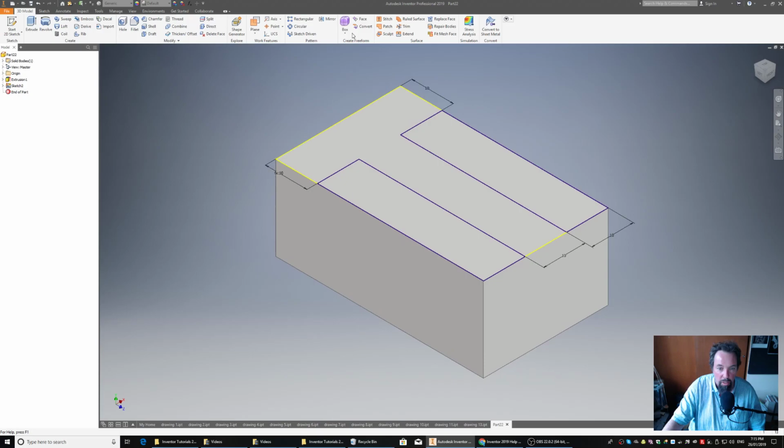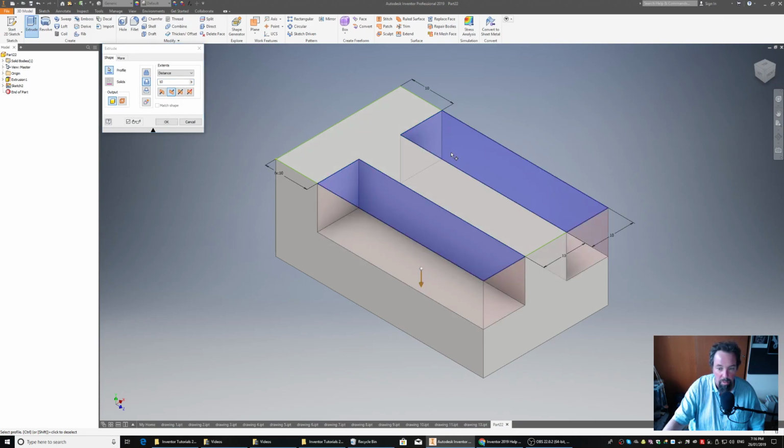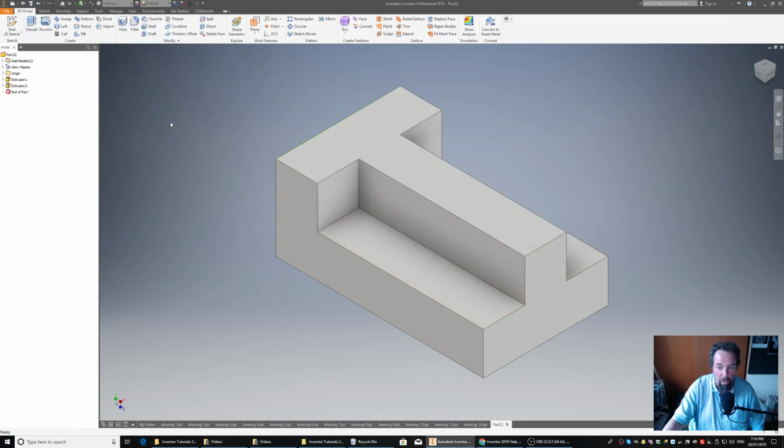Finish sketch. Extrude. So just like we did the last on 13 where we cut 2 triangles out, this time we're going to cut, but we're not going to cut all the way through. We're going to cut to a distance. We're going to cut down to a point, and it's going to be 10 millimeters down. Okay, and I'm going to choose that one, and I'm going to choose that one, and go, yep, that's what I want to do. Okay. So straight away I know what size I've got to be at. There we go. I know how far I've gone down.